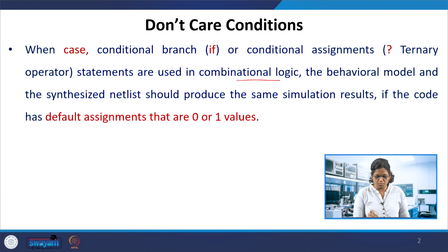The only problem would be the default assignments. If the default assignment is there in the case, yes, it will lead to a 0 or 1 value. Else, if an if-else statement is there, it would also have a 0 or 1 value, or the ternary operator as well. So, this can give similar results if the default cases and mutually exclusive conditions are specified.